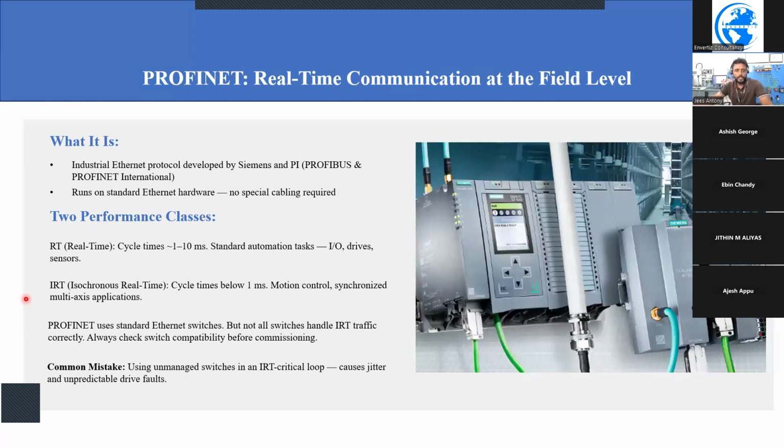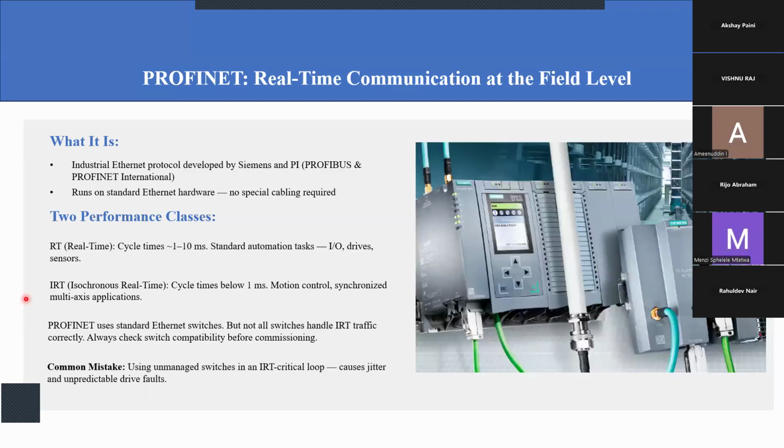We are covering Profinet and Ethernet IP very briefly here. Profinet and Ethernet IP are real-time protocols. When it comes to industrial controller-level communication, real-time communication is very important because most of the signal and data exchanges have to happen in real time to make the control system behave with an expected outcome. Without time-based communication, most control systems could not perform in a deterministic way. That is why we maintain time-based communication protocols like PROFINET, Ethernet IP, and EtherCAT.